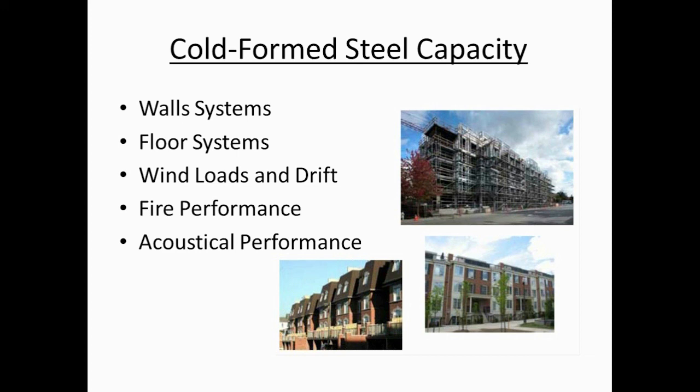Floor systems, we'll talk a little bit about that. There are many shapes and forms. Ultimately, though, the strength-to-weight ratio of cold-formed steel flooring systems makes it ideal for mid-rise construction. They add a lot of strength without adding a lot of weight to the structure, which can be critical. Wind loads and limiting the amount of drift that the building will experience under a wind load condition is critical.